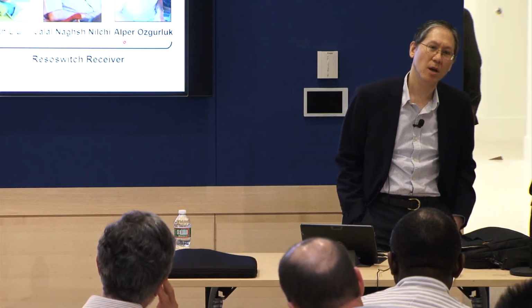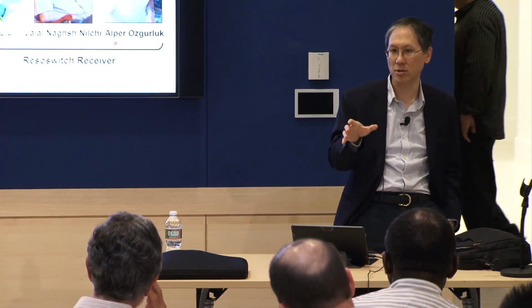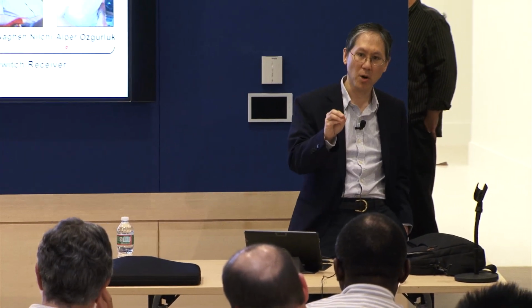And one other question I was curious about, we can talk later maybe, is on the mass. As you keep making the mass smaller and smaller, does that hurt you in terms of the Brownian noise? Yeah, so there's all sorts of issues that I'm not mentioning here, but that Brownian noise actually really comes down to just what the equivalent circuit is of the device. So the equivalent circuit is an RLC circuit. The R entirely models that Brownian noise. And if you think about it, FBARs have an R of 50 ohms or less. Once these things are 50 ohms or less, that's very little voltage noise, actually.